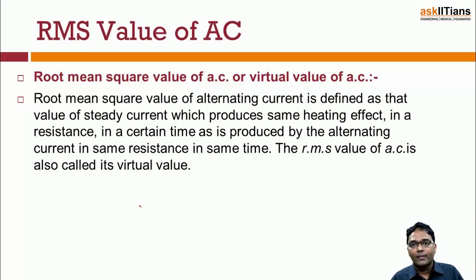Obviously you define everything in terms of effect. So it produces the same kind of heating effect in the resistance as the same alternating current that is passed through the resistance, right? That's the reason this is very, very important, because it gives a kind of analog to the DC.